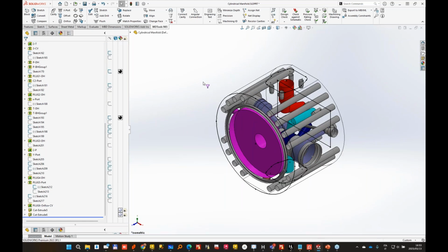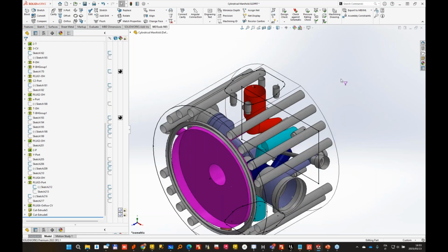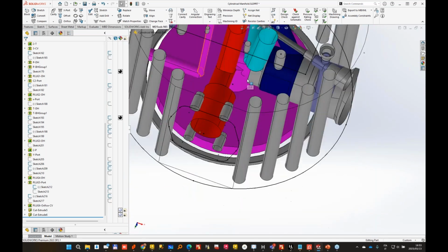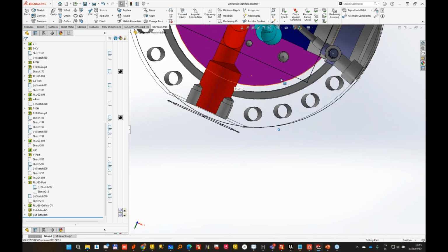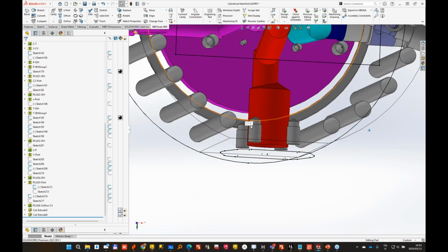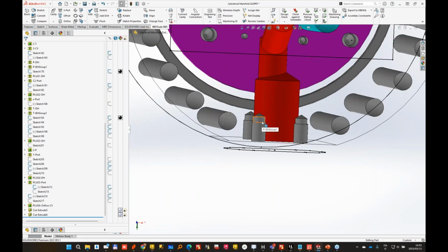Back to the question of where the drill depth is starting from, I want to highlight this because this is really an important case. The drill depth is always made from the face where it started.